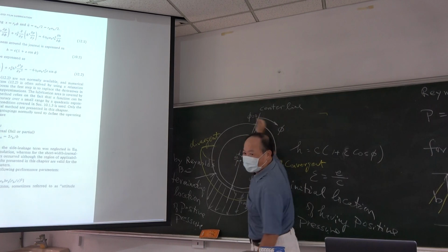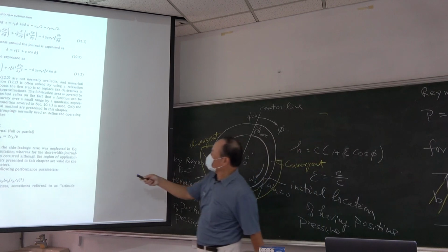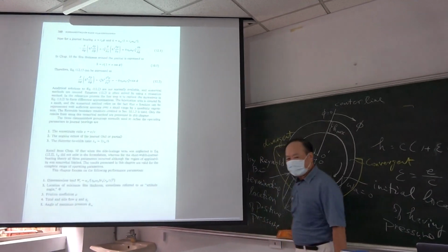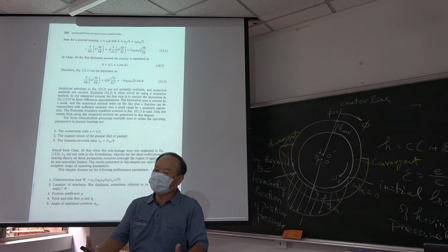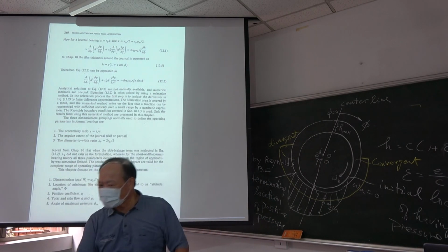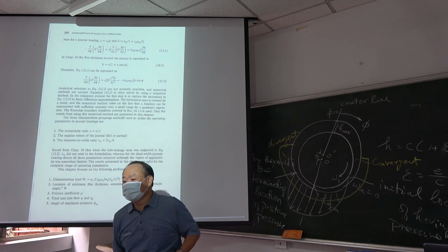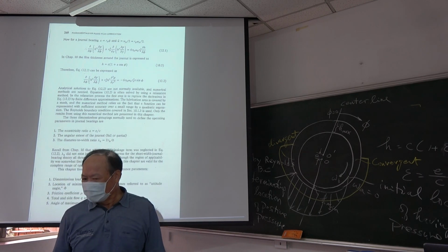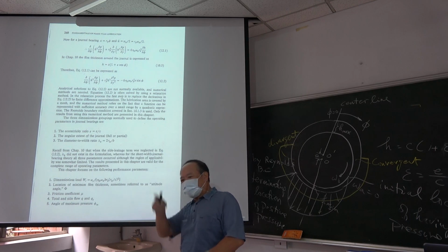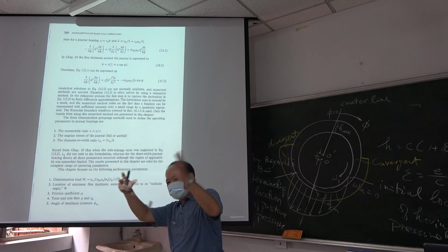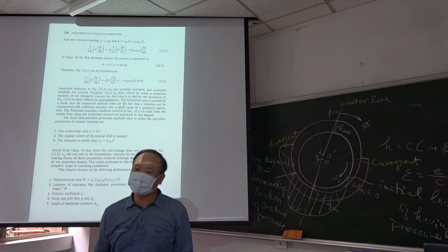We don't have this portion. This we call the partial arc. For example, some conveyor just moves something, some heavy body. In this case, we don't care whether the motion is in high precision, so you can use the partial arc. But if high precision is needed, like an electric fan or some rotating machine, in this case you have to use the full journal bearing.